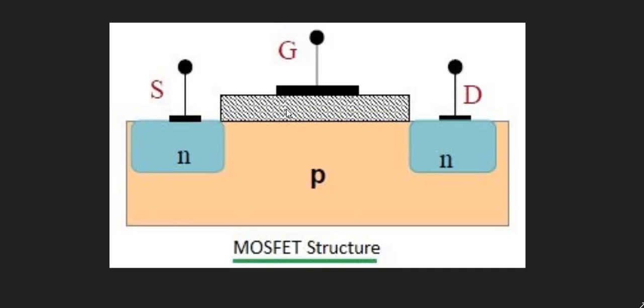If you look here, we have this structure, and this is called an insulator. The reason we need an insulator is because we want a capacitive charge, which just means we use an electric field to switch this on. So we don't need contact. As long as there's an electric field here, this can move. What's going to happen now is that there is a small voltage which we must overcome before the electrons start moving. That little bit of voltage is called VTN, the threshold voltage.